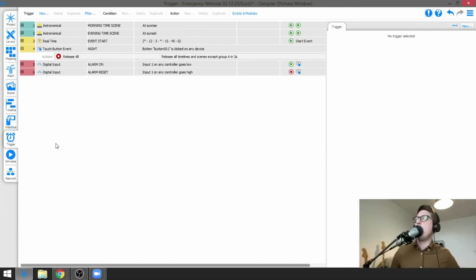We do have a Rio device that is capable of controlling outputs, but I believe its maximum voltage is 48 volts. Is that correct? Yes. So you could have a Rio control the power going to a fixture, but the 48 volt limitation is there, and you can't really use more than 48 volts because you'll blow the output.